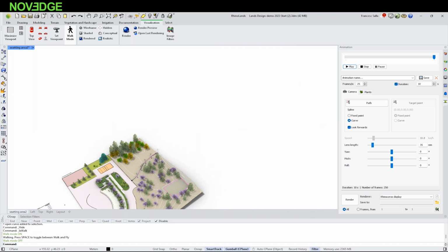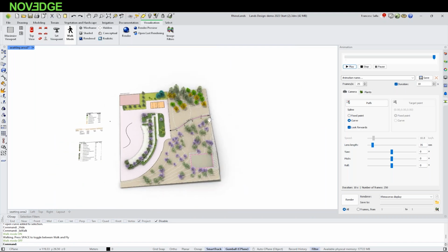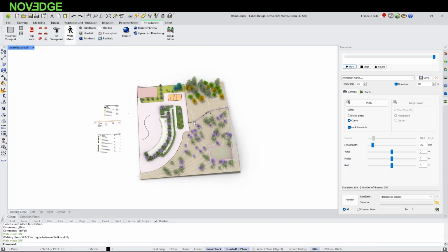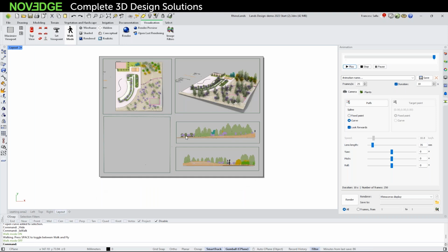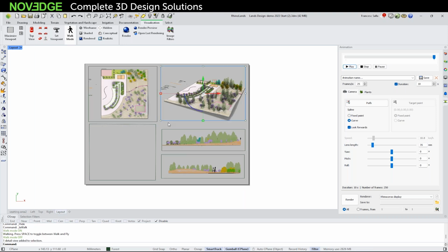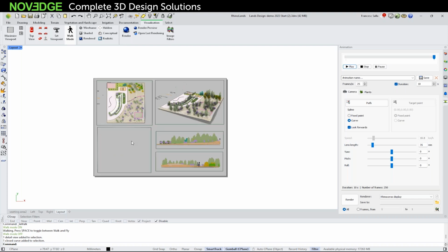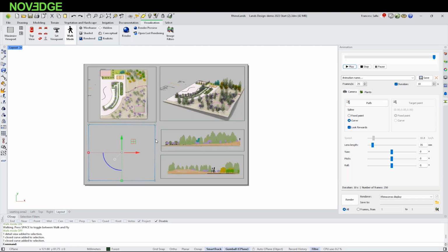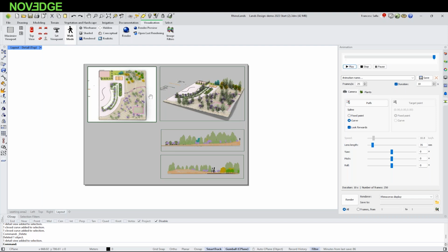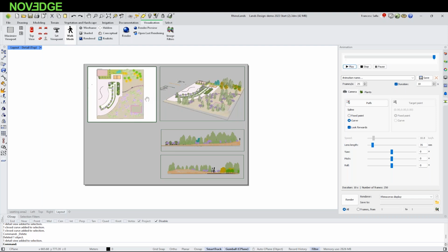All right. And also, if you want to present the project, the plans of the project, we can work from the page layout. Here we already have a few details. Details are the viewports to the model space. If we click inside here, this is just a curve. So we can add, yeah, this is a detail. This is actually a viewport to our model.